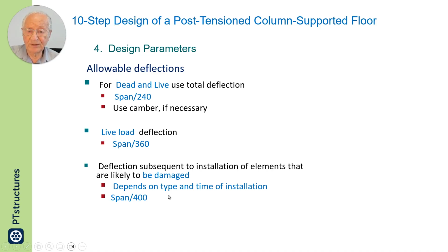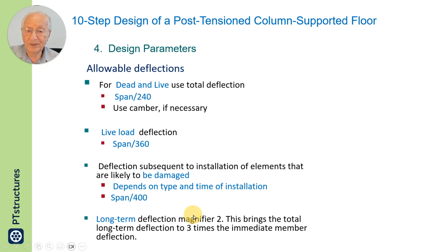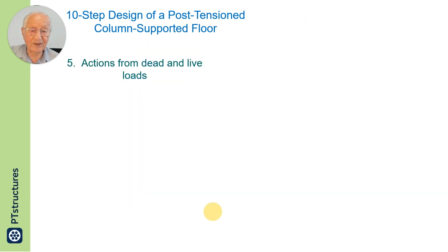The most critical one to consider in design is live load deflection. Others are amenable to control. Long-term deflection is calculated by assuming a magnification factor of 2 due to creep on the immediate deflection.